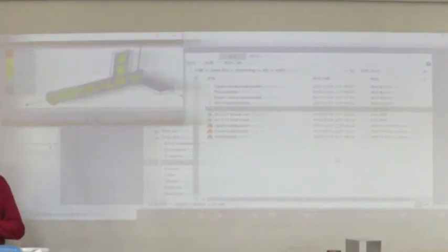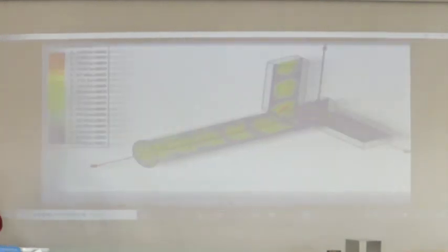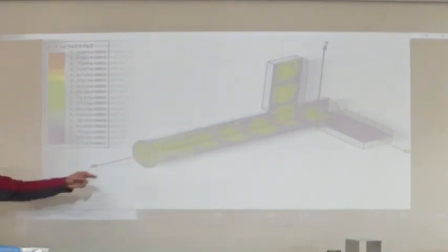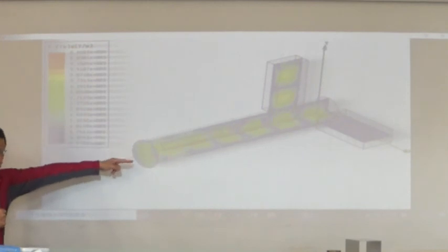If you control, just like this case, if you inject the signal from the other side, 90 degrees perpendicular to each other, then it will excite a circularly polarized wave.